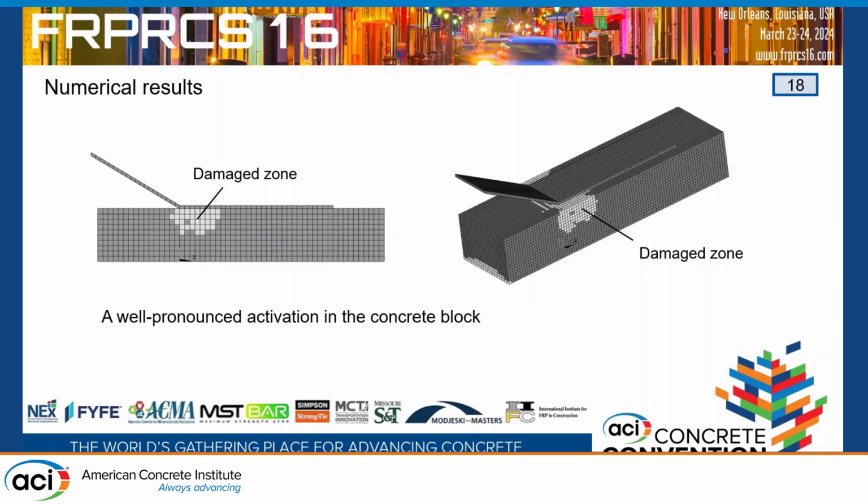Thank you, Mariana. So I have a question. How did you get the parameters for your cohesive elements? Basically to match the experimental results. First we got the parameters for concrete, the model parameters. Then we used a suggested split of the contribution of each fracture mode. This split allows a rough assessment of the fracture energy for mode 1 and mode 2. And therefore we try to have the same area under the curve.